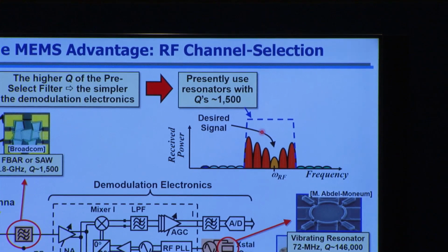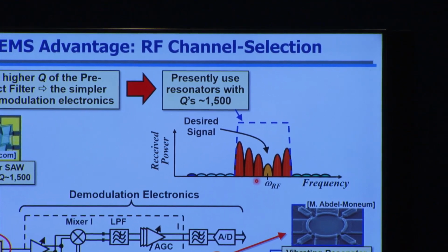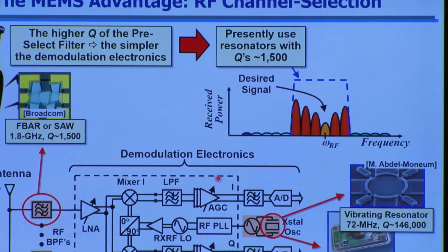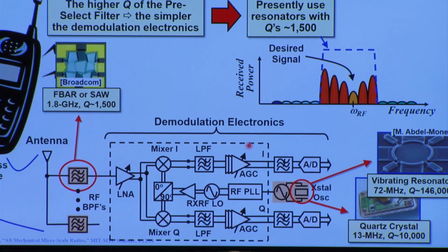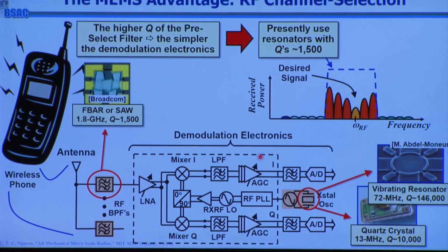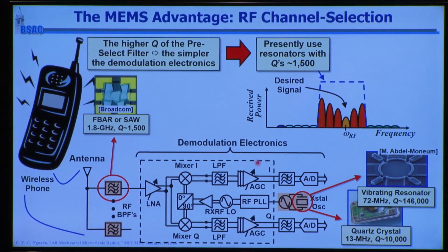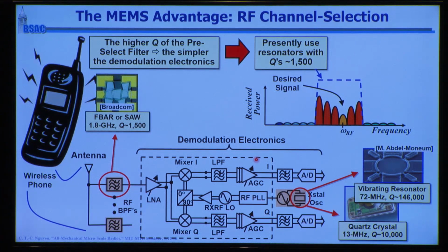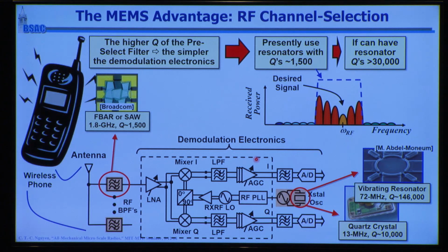So now suddenly you get rid of that interference problem. You can lower the power consumption of the electronics. They can be a little more nonlinear. And so now suddenly your phone can last, what, a day or two on a charge. And you can ask yourself whether you're happy with that. Okay? If you're not happy with that and you'd like your phone to last longer on a charge, then one thing you can do is try to increase the Qs of these resonators.